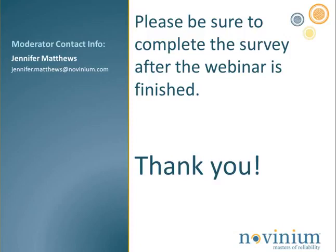So that's one that currently falls through the cracks. So in short, they're somewhat interchangeable, but not universally interchangeable. Right. The ones that are called out in 386 are universally interchangeable. And by the way, something I did not mention, the next revision of IEEE 386 is going to change the dimensions for the 15 and 25 kV interface, so that if by chance someone uses the 35 kV stud, if they do get mixed up, it will not bottom out. The old version of that interface affects very, very few. In fact, I believe only one utility anymore, so it won't be an issue.